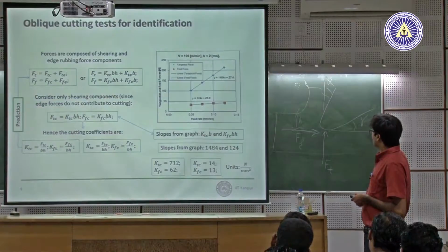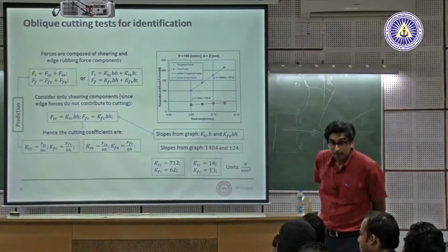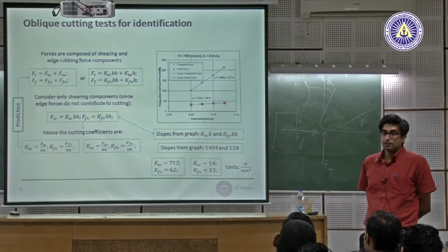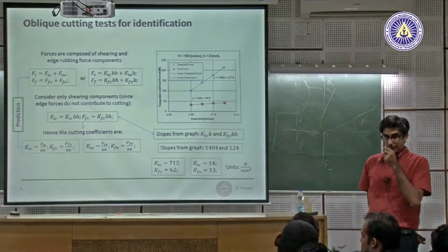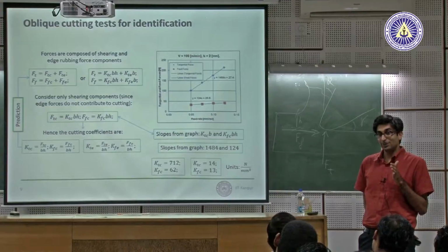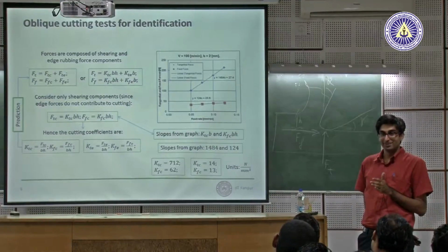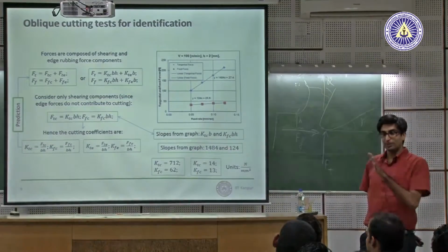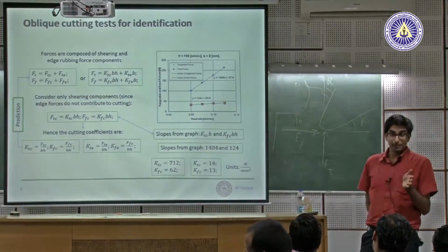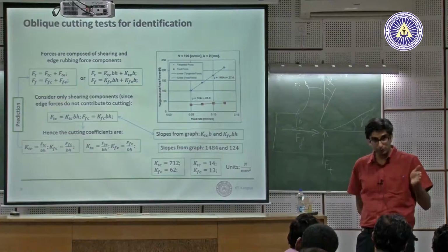It depends on only V, not only the motor. The spindle speed you can change either by motor or by parameter V. No, this is a servo motor. You can change speed continuously. It's not the AC motors that you're thinking of which have a fixed speed. If it's 1500 RPM, you can only run at 1500 RPM, for example. If you want to change the speed of the motor, you have to change the motor, or use a VFD, a variable frequency drive. This is a servo motor which allows you to continuously change speed.